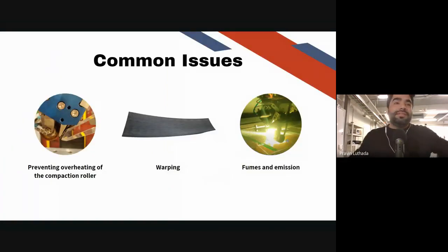So the overheating will happen because the motion systems have to get to some velocity, they have certain acceleration, and it's during this acceleration period where there is either a burst of energy or a lack, and then there's no bonding. So you would usually have more energy, and then you would end up burning this bit. So you really want to have cooling, water cooled and air cooled.